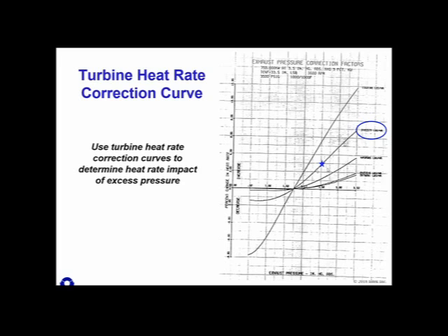So then you would put in the measured condenser pressure. So let's say our condenser is operating with this duty at 2.5 inches. And based on previous work using the models that we just talked about, you calculated that the condenser should be operating at 2 inches. With the cooling water flow rate you've got, with the cold water temperatures you've got, you should be operating at 2 inches.